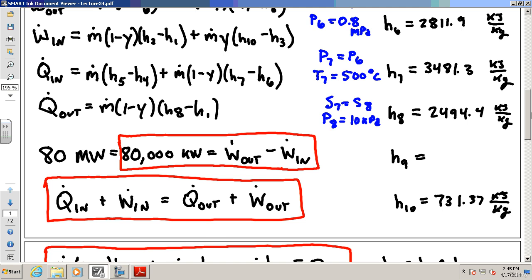Oh yeah, H10 is 10 MPa. So you get H10 from H3, right? You go from 3 to 10 using the pump, right? So it's the same thing as what we did from 1 to 2. You do the same analysis from 1 to 2 as you do from 3 to 10.